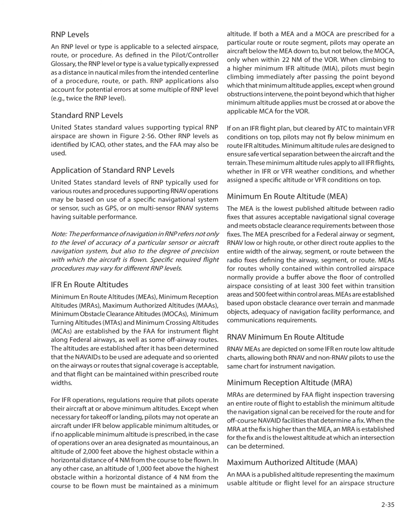MEAs are established based upon obstacle clearance over terrain and man-made objects, adequacy of navigation facility performance, and communications requirements. RNP minimum en route altitude. RNP MEAs are depicted on some IFR en route low altitude charts, allowing both RNP and non-RNP pilots to use the same chart for instrument navigation.